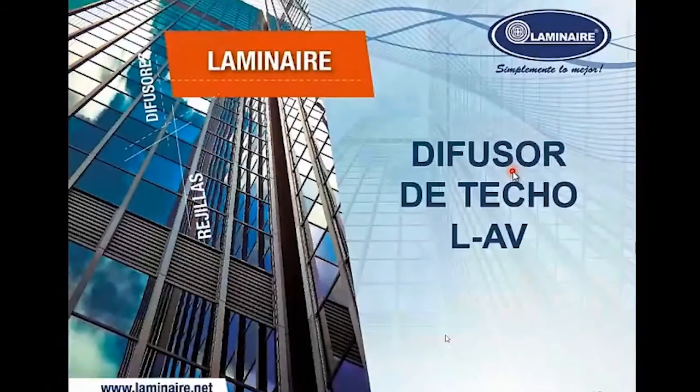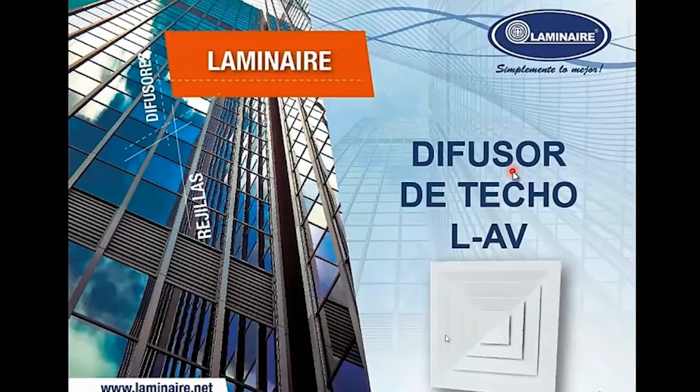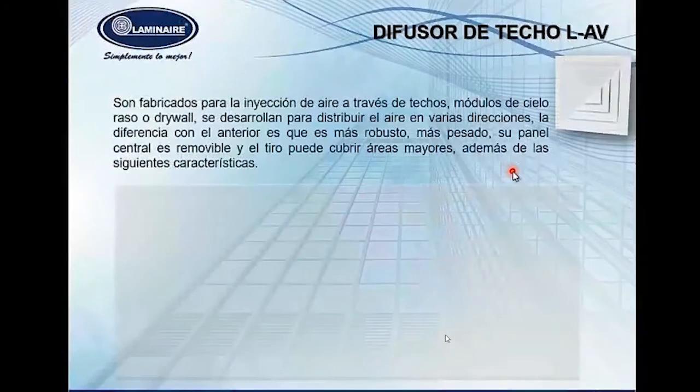So right now we're going to talk about the ceiling diffusers, LAV. They are different from the LGS because they have a central panel in the structure and in the geometry, so there are some different geometries. They made this LAV diffuser to have better performance characteristics compared to the other diffuser, because they are manufactured for injection through ceilings in dry walls. They are developed to distribute the air in different directions.